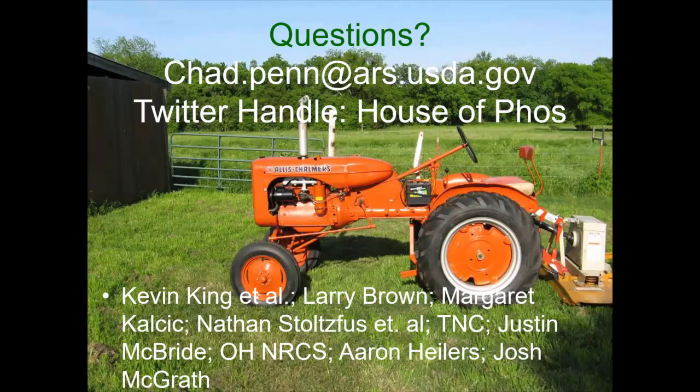Yes, sir. How do you keep the material from sedimenting in? How do you keep fine particulates out? Okay, the question is, how do we keep fine particulates from clogging these things up? And the answer is, you should use other best management practices to prevent particulate soil from getting there in the first place, right?